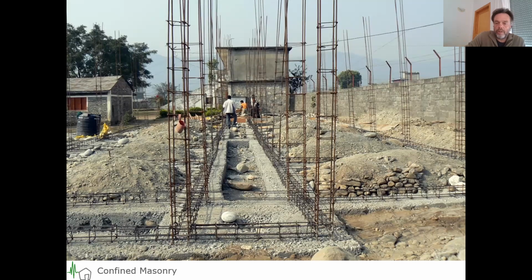So the steel is already there, but you see there's far less steel needed than what you would need in a concrete frame. The spacing in the middle of the columns is quite large. The closer you get to the connections, the spacing gets a little bit closer, but it is still only 4 horizontal bars. That's it. So this is where you save costs.